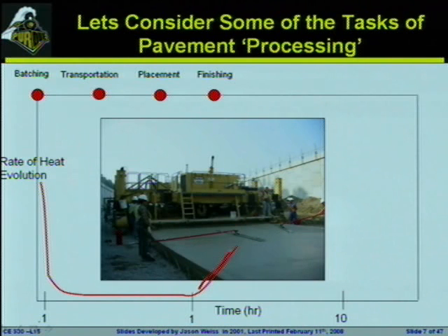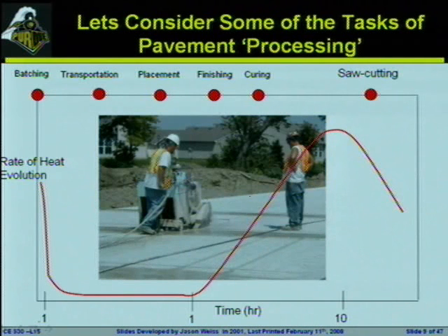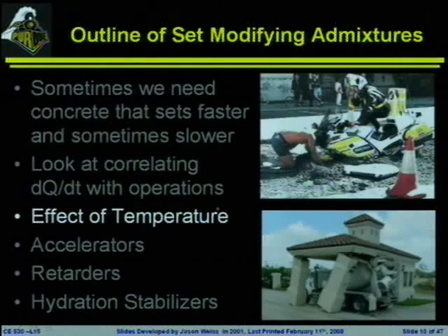this is, you want this to happen before the temperature starts to rise, before the temperature starts to go up. Basically because now the concrete is going to start the process of going through initial set. They're going to be placing the curing on during this period, and there's going to be rapid hydration taking place during this period. Curing compound being sprayed across the surface, the curing compound being white here so that you can tell where it is and so that it'll reflect a little bit of energy. And then typically you'll start to see the temperature or the heat release going down, and that's typically when we're getting on the concrete to be doing things like saw cutting and other types of construction operations.